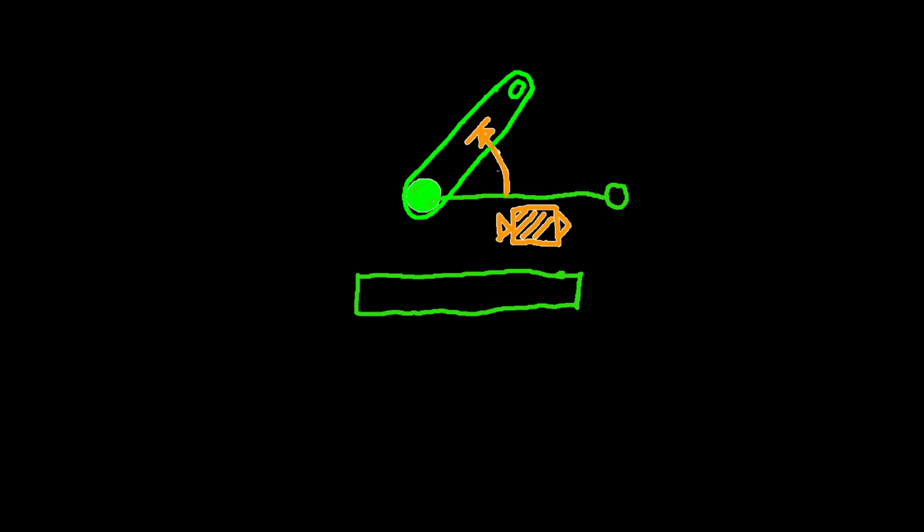So start with a base part and add a line. The mechanism has 0 degrees of freedom. Now add a part and it has 3 degrees of freedom. A pin joint will take away 2, leaving 1 degree of freedom. Add a motion dimension, taking away the last degree of freedom, leaving 0. The green parts have 0 and the blue have 1 or more degrees of freedom.